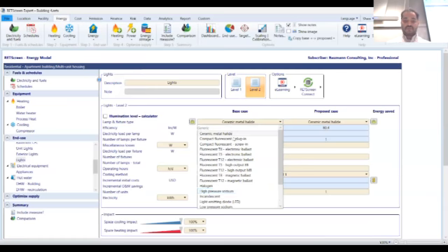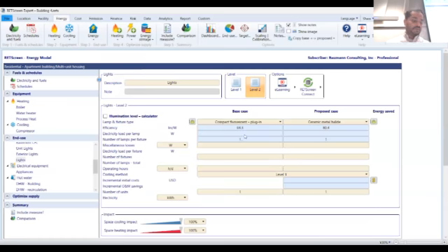I have compact fluorescent plug-in lamps with a 13 watt electrical load. There are miscellaneous losses, but I'm assuming there are no losses through it. The number of fixtures that we have is 7. It is operating 24/7. The quantity, the number of units I have determined, is 5. And it is currently contributing 100% to my heating cooling load.